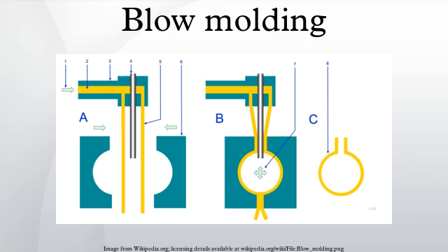Spin trimming. Containers such as jars often have an excess of material due to the molding process. This is trimmed off by spinning a knife around the container, which cuts the material away. This excess plastic is then recycled to create new moldings. Spin trimmers are used on a number of materials, such as PVC, HDPE and PE plus LDPE.